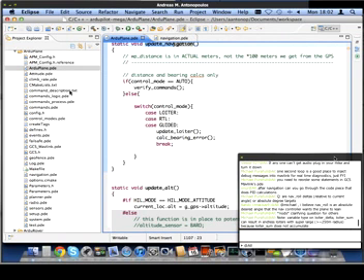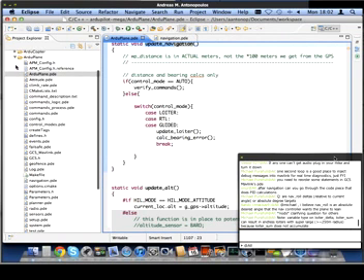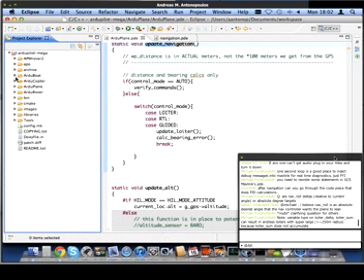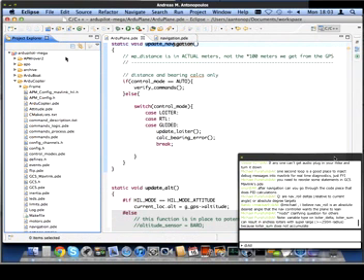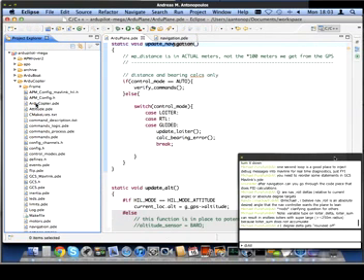It gets a little bit more complex when you've got an airspeed sensor, because it does more fine-grained control based on the throttle and an energy calculation based on your total kinetic and potential energy of the aircraft. But for the non-airspeed sensor case, it's relatively simple. Basically, if it wants to go up, it raises the pitch, and if it wants to go down, it lowers the pitch.